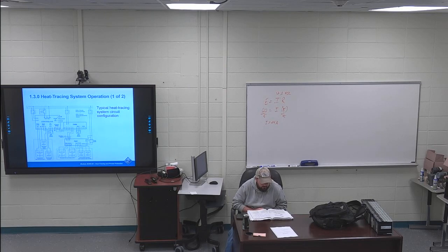In some systems, temperature monitoring systems are communicated to the controller by means of power line carrier technology. In such systems, a power line interface unit, PLI, receives temperature and continuity inputs transmitted over heat tracing circuit power wires from special end-of-the-line heat cable circuit transmitters.